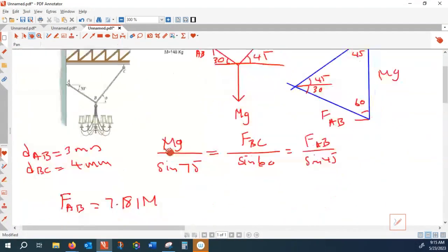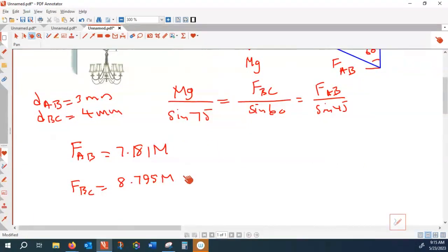Excuse me, sir. Can we do it by resolving the forces to the area? That's a normal stress. These are normal stress. Can you make the components of each force x and y and then do it? Solving the free body diagram, yes. But I thought that was easier this way. If you're more comfortable with Cartesian, you resolve the forces in x and y. That gives you two equations, two unknowns. You have to solve them at the same time. Yeah, you can do it that way.